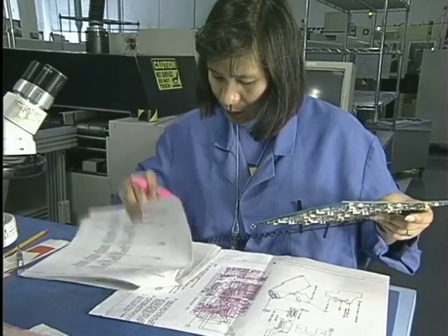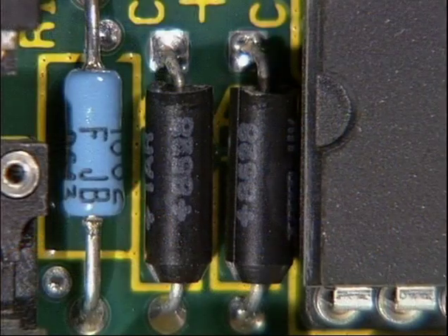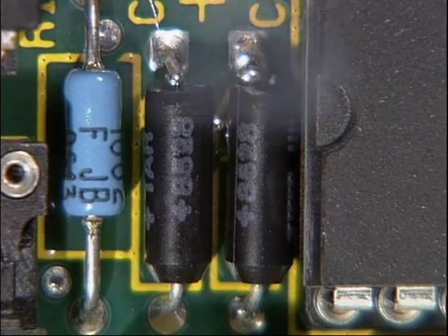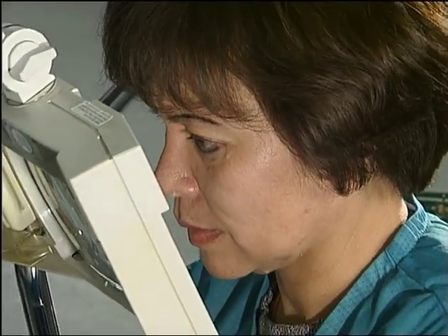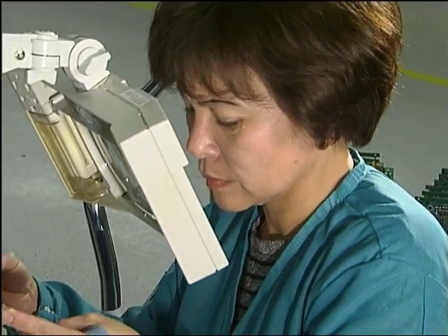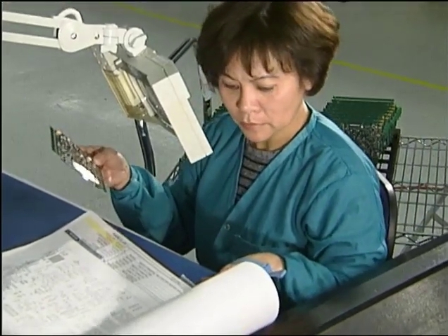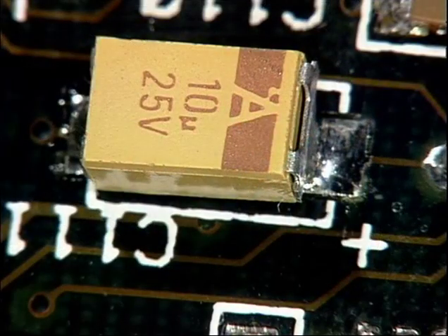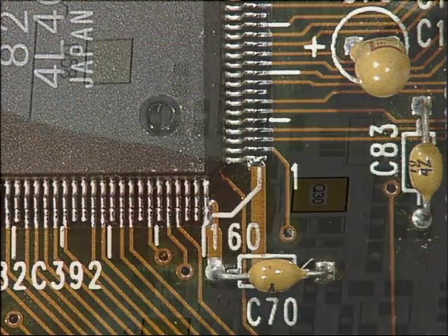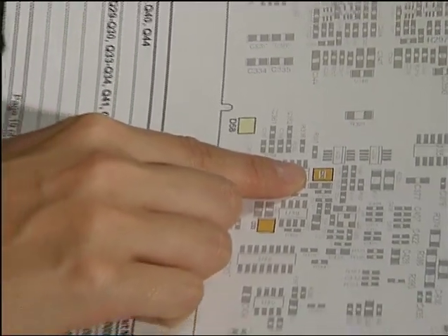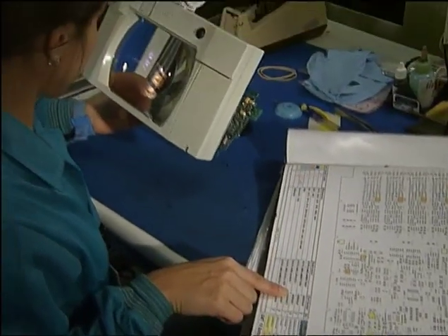Identifying components correctly is one of the most critical jobs in electronics assembly. Improper component ID can result in damage to the component and circuit board. It's important to understand part numbers and CRDs, along with component values and tolerances. And you need to be able to verify polarity and pin 1 orientation. Careful attention to detail will help to make sure that your company's products work properly and reliably. The more knowledge you have, the better you can do your job.